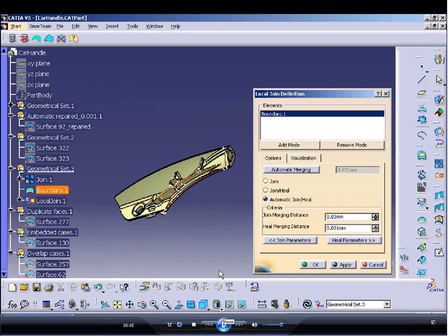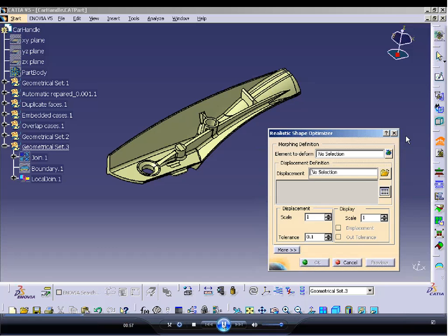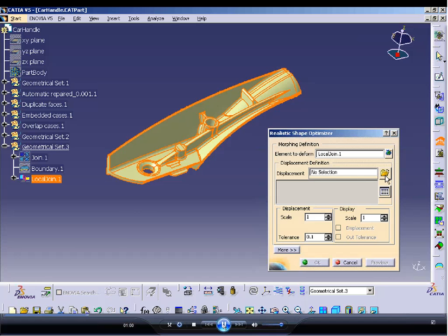So in this case here, it also includes something called the healing assistant, which allows you to come in and take surfaces from parts, from STEP files, IGES files, doesn't matter, and quickly heal these surfaces and turn them into a solid. So that's what that tool was.